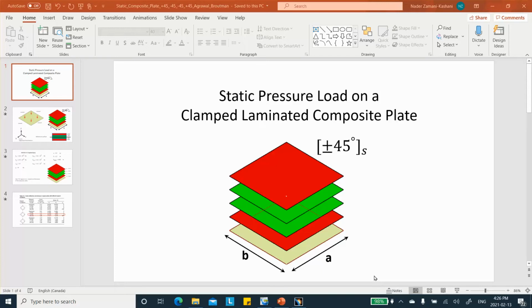You have to do a genuine FEA analysis. So what I'm doing now is a series of newer segments where you do a static analysis, and then we're going to follow it up with transient dynamics. By the way, the last one that I did dealt with finding natural frequencies of a composite structure, or composite plate in that case. Even there, you had to do a genuine FEA calculation as opposed to just going to a matrix solver which handles ABD matrices.